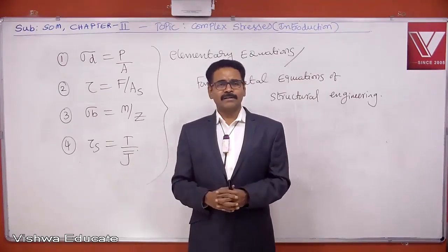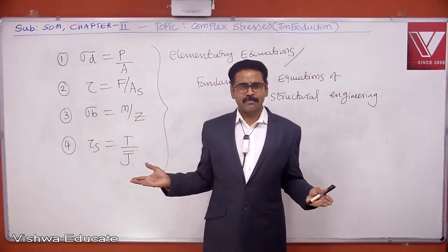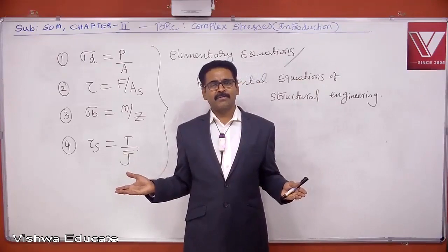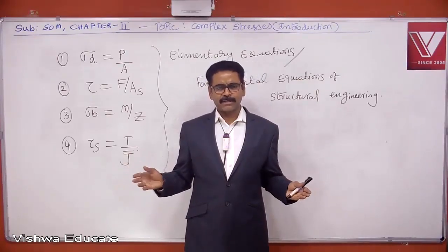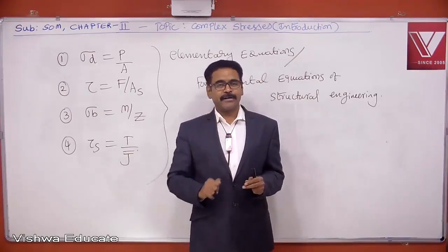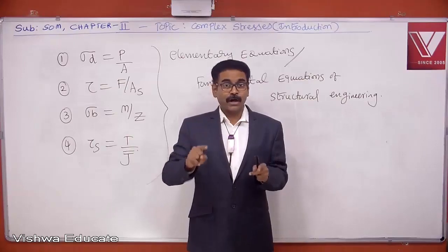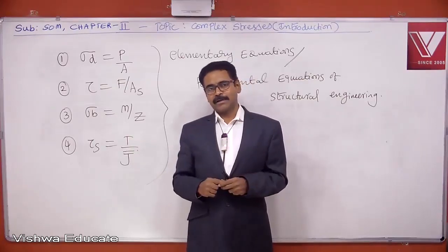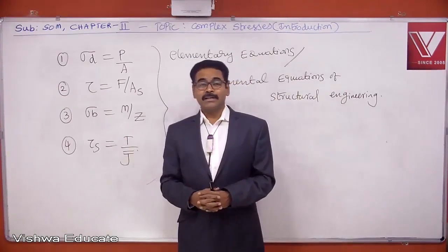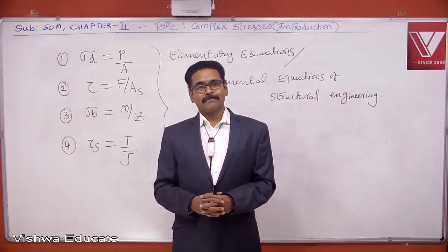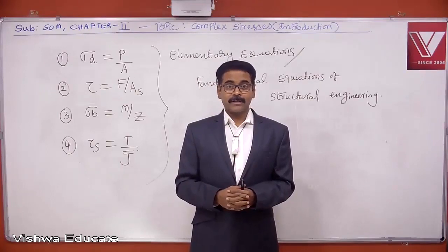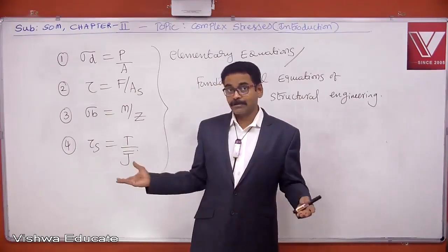While designing any brittle structure, these two are important. What is the magnitude of major principal stress? What is the angle of major principal plane? You should know how to find major principal stress, minor principal stress, angle of major principal plane, and angle of minor principal plane, especially while designing brittle structures. You should know how to find principal stresses and the angle of principal planes. This is the third reason.